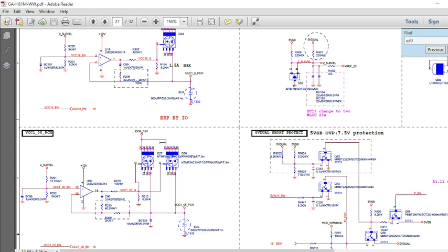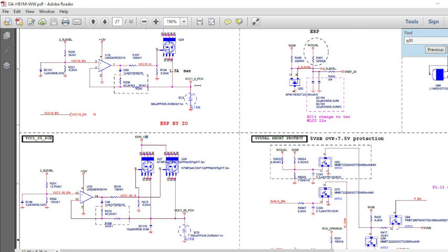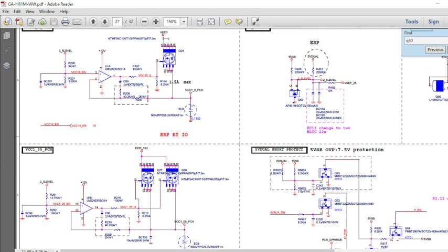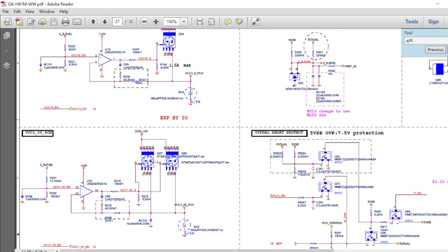These are getting 1.5 as an input, because 1.05 is less than 1.5, so we can give that DDR supply as an input, and they have given it. In the previous case we can't, because 1.8 is greater than 1.5, that's why we used 3.3 over there. So in this 1.05 section we have this DDR voltage as an input to both MOSFETs, and again the gate of these is controlled by the same LM324 IC, because it has 4 operational amplifiers. So here you should get 1.05.